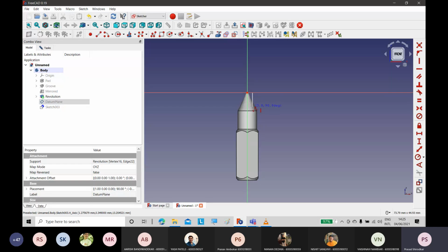So just make sure some part is vertical. Right, after that, after you make it vertical, then use the toggle key M till you get the arc, and approximately make sure that your arc is like a quarter circle, so that your geometry doesn't go haywire. Right. So click and then again click on the M option till you get this vertical line, and make sure you have the vertical direction constraint appearing, so that it becomes a vertical straight line, and then just close this curve.